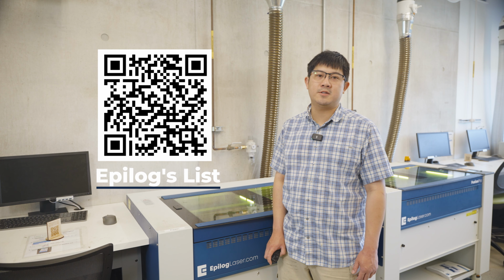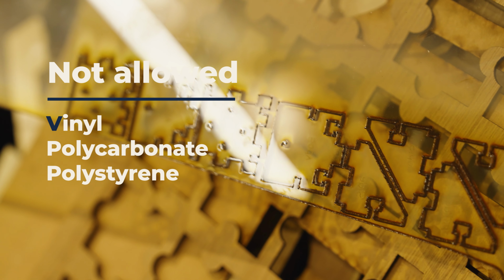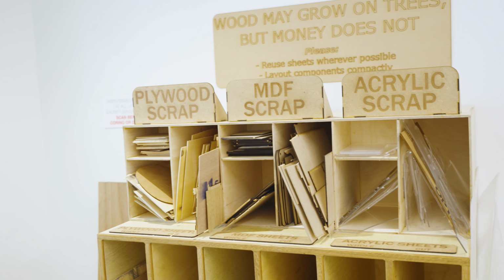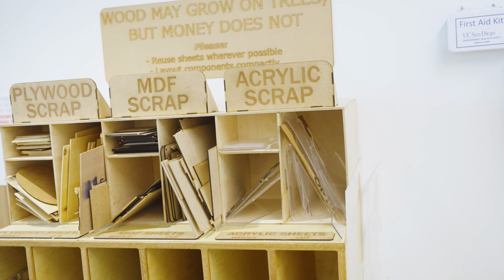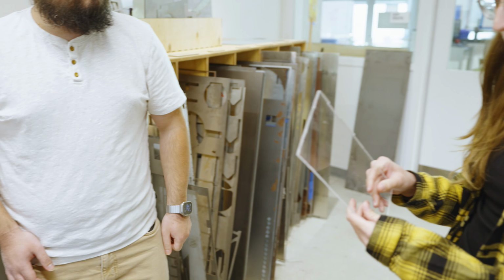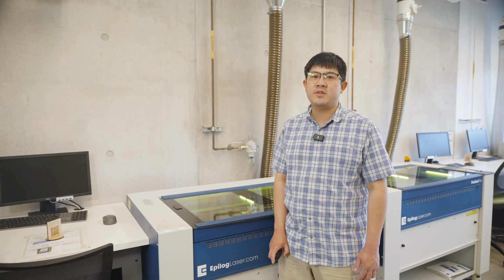Unfortunately, there are several materials that are forbidden and should never be used in any of our laser cutters, mainly plastics like vinyl, polycarbonate, also known as Lexan, and polystyrene. We stock a wide variety of known safe materials that you're encouraged to take advantage of. If you bring in any outside material, please double check the material specs and have one of our staff members sign off on it before cutting to make sure everyone stays safe. Many of the dangerous materials can be easily mistaken for safe ones.